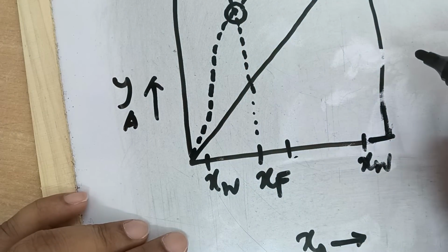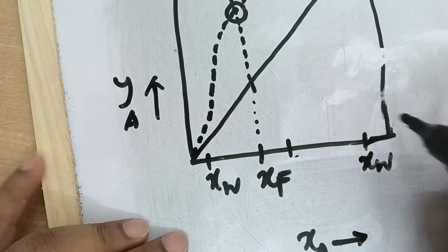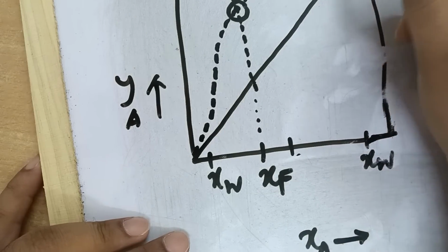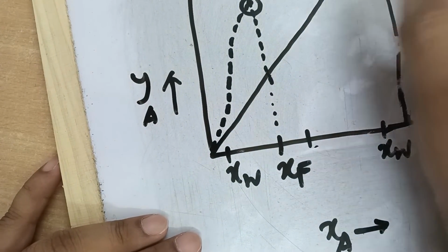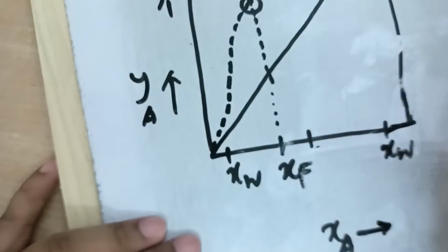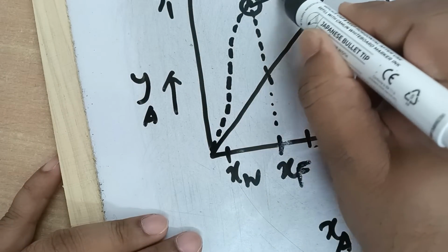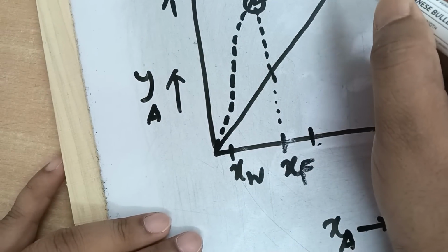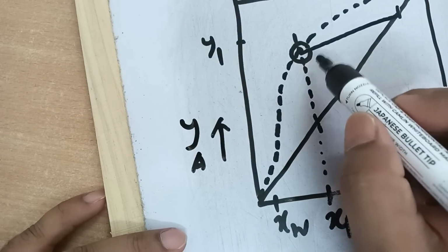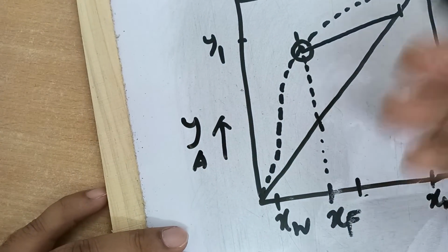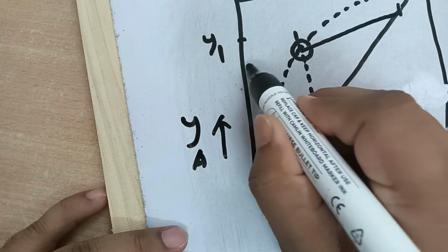Fine. And then, as per the earlier practice, from the y equal to xD point, you let the enriching section line emanate, intersect the point of intersection between the feed line and the equilibrium line, and extend it.